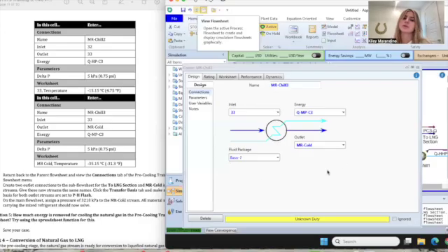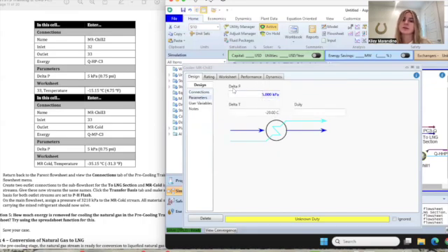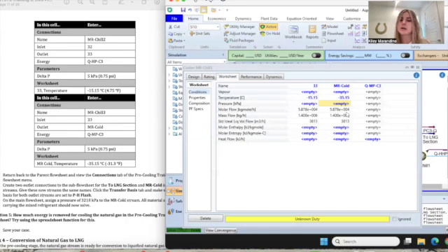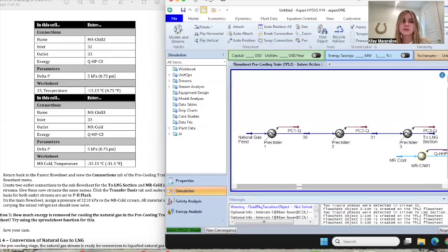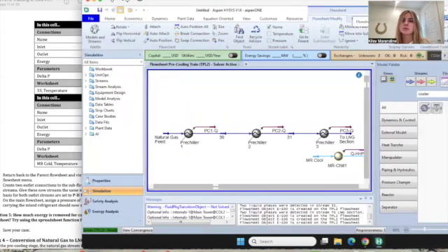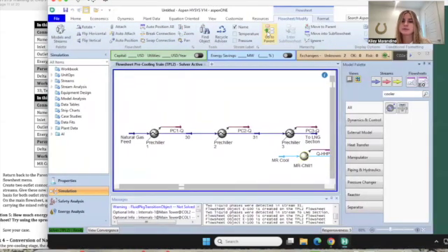So for our last one, the way I defined it is the same as they give us here for our specs, called MR chill 3, inlet stream 33, create an outlet MR cold, energy stream Q-MP-C3, and parameters, delta P is going to be 5, and in worksheet, MR cold temperature is going to be negative 35.15.